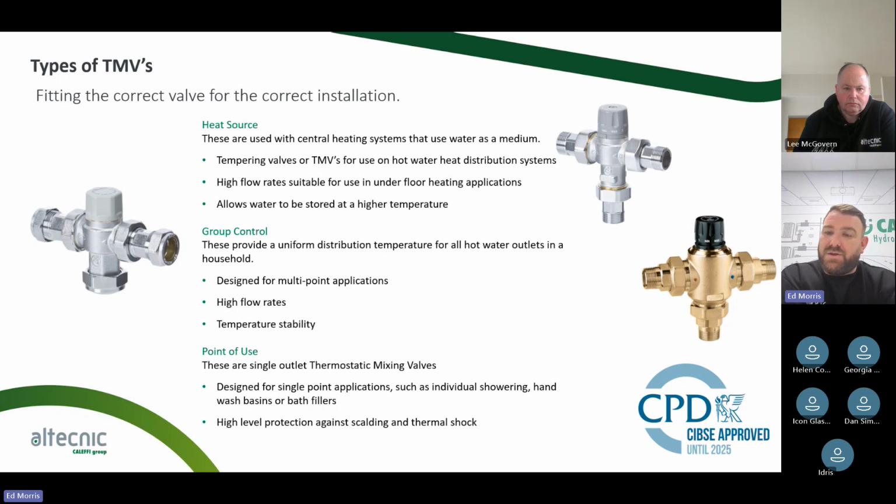But if we think back to where we were with bacterial control, for instance, if it's a football club, the showers may only be used once a week. So you have to design into your system ways to sanitize that system, because you're creating dead legs by its very nature. So always design into the system a way of sanitizing through that should you be using group control.